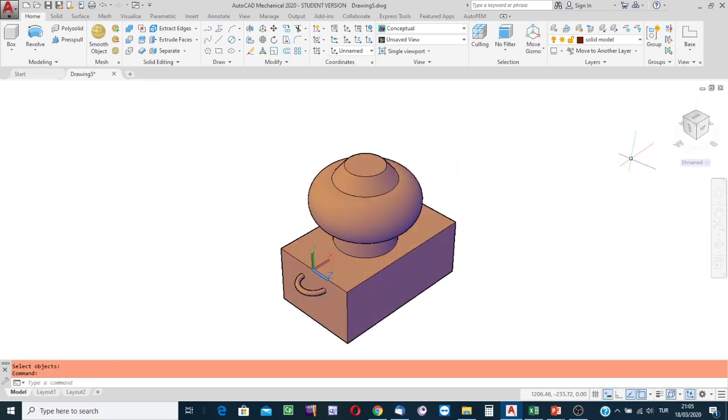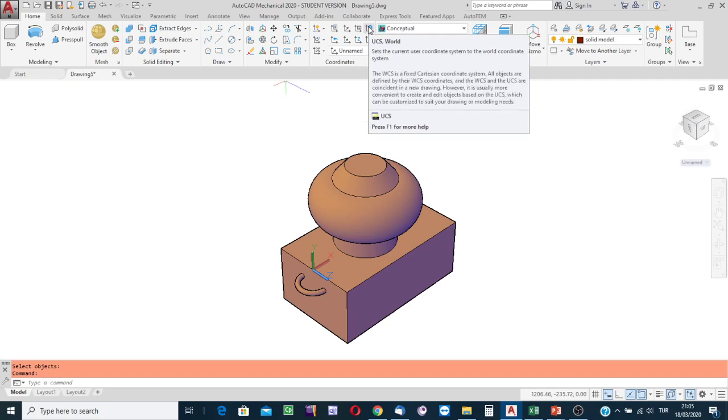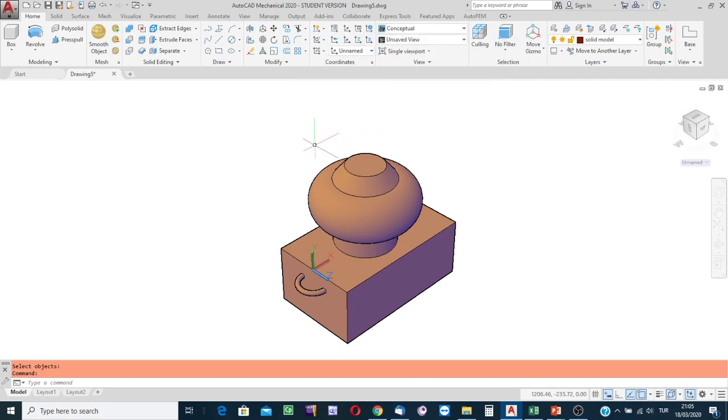No need to have the coordinate frame connected to the model. It is a poor practice. Click on the world coordinate button, and then shift it from its special location to its world location. Click. Yes, the coordinate frame is at its world location.